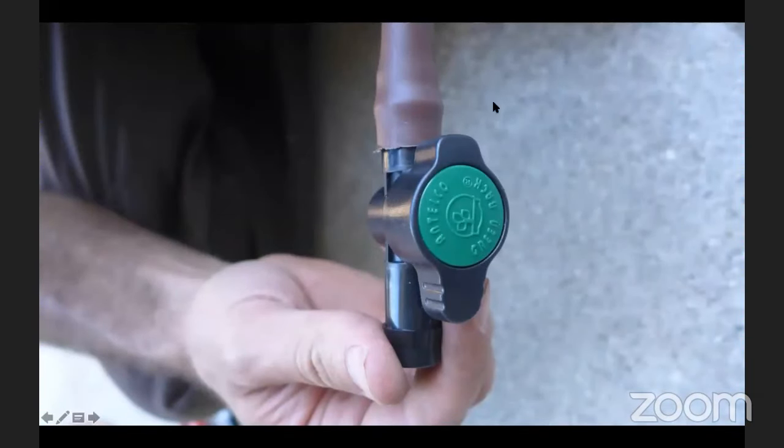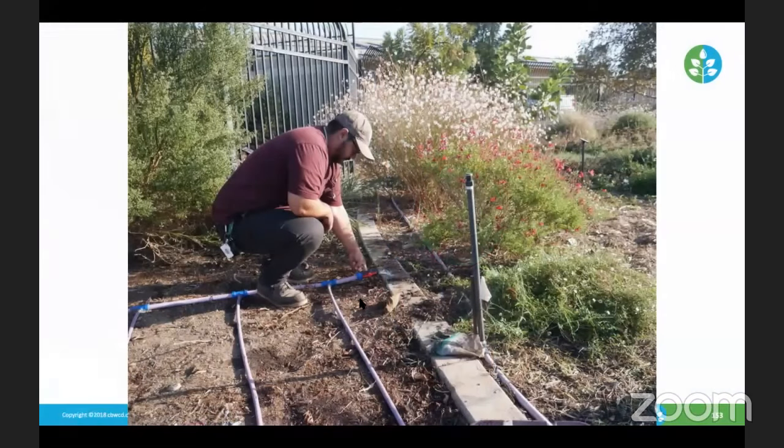Another flush valve. This is going to be installed in your drip irrigation system, typically at the end of the line. So this is an on-off valve. We always want to flush the tubing as well. Here's my coworker Daniel. He's opening this up and flushing the zone. Even though we have a filter at the valve, it's always good practice, at the same time that you flush the irrigation valve, to also go to your system and flush the system, just in case there's any debris. If you do it at the same time twice a year, you're ahead of the game.